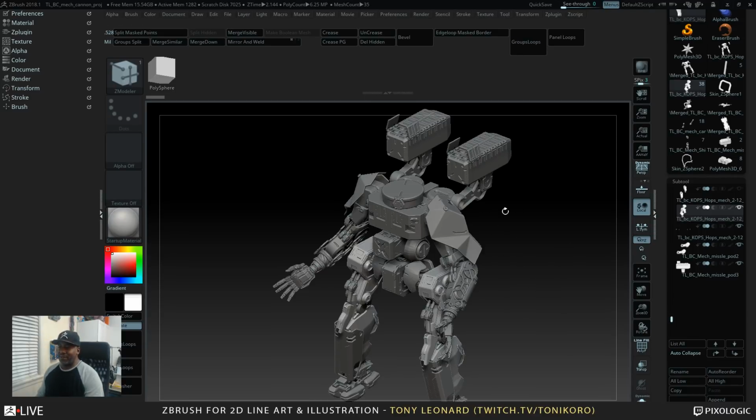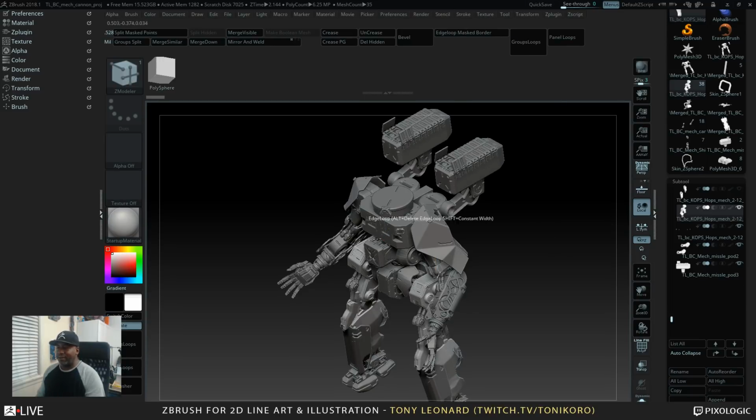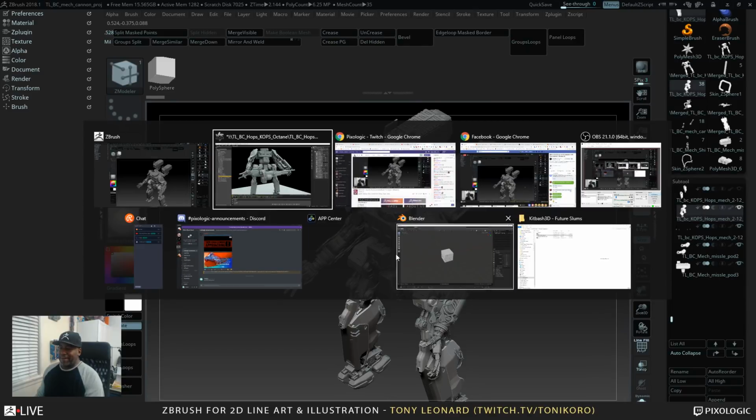You can probably slap UVs on a lot of this geo, even if it's triangulated. I'm sure you could probably make material IDs. And then just for conceptual sake, you could bring it into either Quixel or Substance and start building up your own textures and applying them in a procedural fashion. Sometimes what I'll do is take shapes like this into Octane, and then drop a normal map of a texture, and it procedurally box maps it around the object, and I can affect the change or the bump of that to make it look more like an actual physical material. Anyway, let's get back to it.